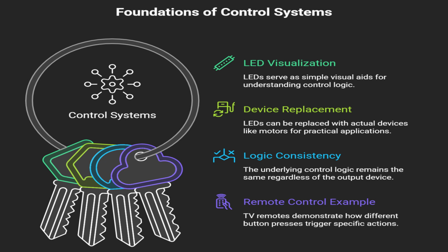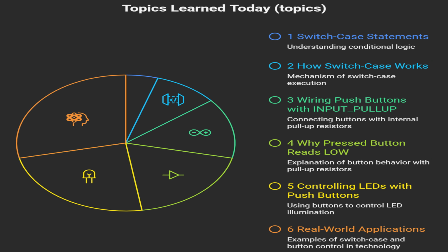That is it for today's lesson. Today we learned what the switch case statement is, how switch case works, how to wire up multiple push buttons using input pull-up, why a pressed button reads low, how to control multiple LEDs using multiple push buttons, and how this same concept is used in remote controls. I hope you enjoyed the lesson and learned something new.